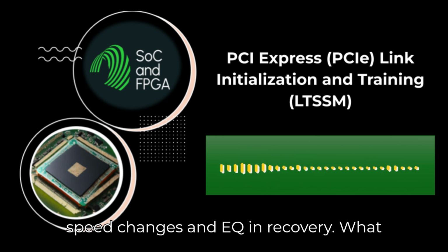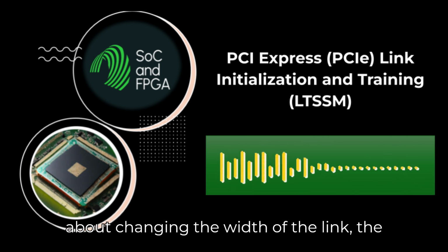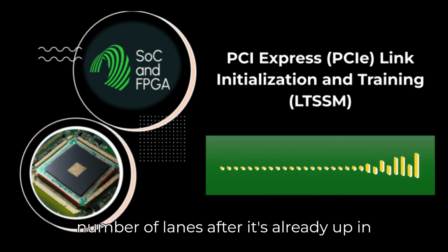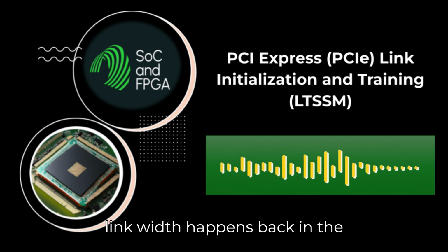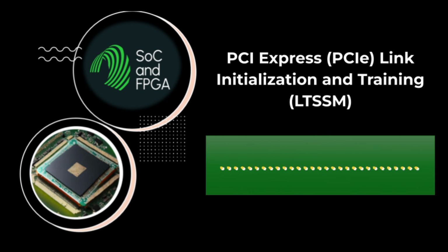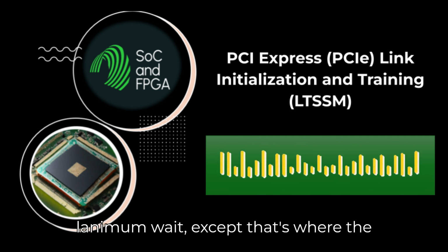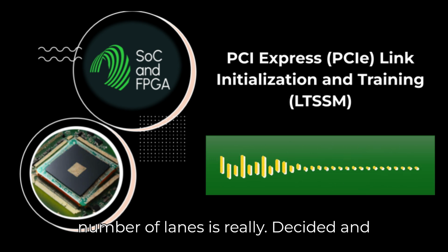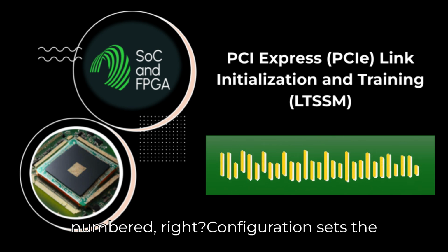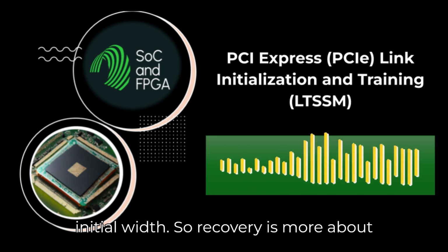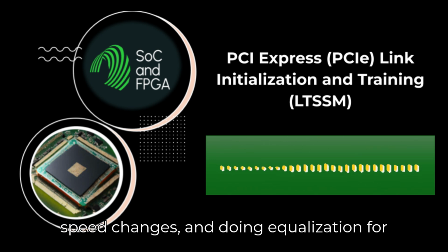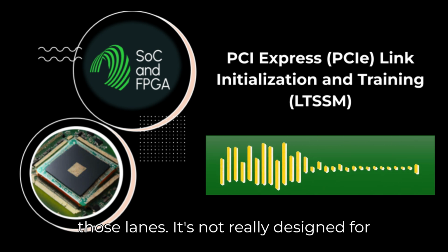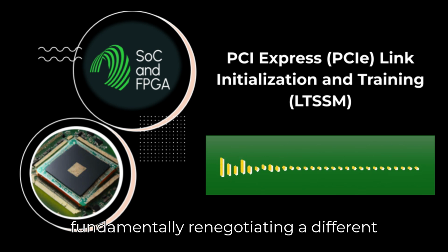We've covered speed changes and EQ and recovery. What about changing the width of the link, the number of lanes, after it's already up in L0? Does recovery handle that too? Not primarily, no. The main negotiation of link width happens back in the configuration state, remember. Configuration.LinkWidth.Start, Lanenum.Wait, that's where the number of lanes is really decided and numbered. Right. Configuration sets the initial width, so recovery is more about... Recovery is mostly about maintaining stability on the existing lanes, handling speed changes, and doing equalization for those lanes. It's not really designed for fundamentally renegotiating a different number of lanes.